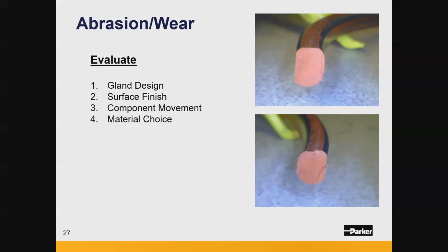You also definitely want to take into consideration the nature of the dynamics of the application, and make sure that it doesn't involve motion that's too slow, but also, of course, too fast. And you want to consider your material and make sure you have a sealing compound that is sufficient for dynamic applications. We never recommend, for instance, a silicone compound or a fluorosilicone compound for dynamic applications. We would prefer to go with something like an HNBR that's more wear resistant on average, or something like an internally lubed compound as well.